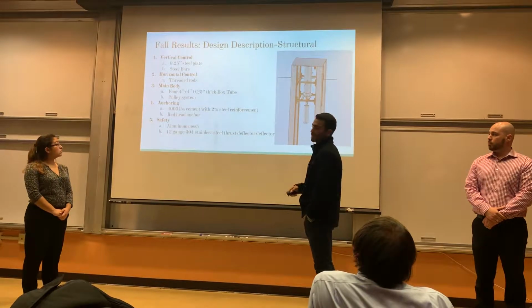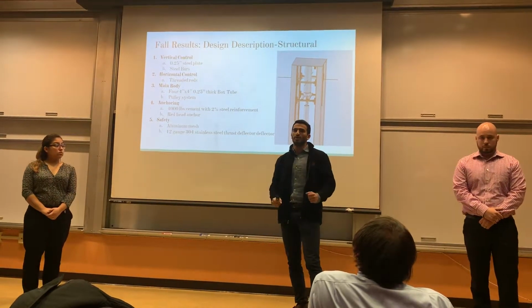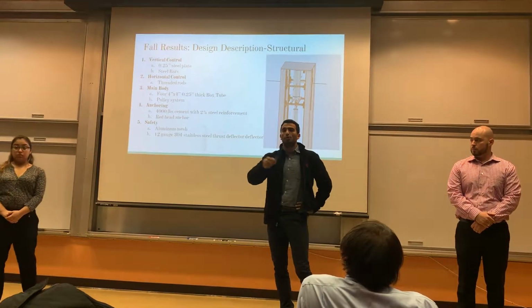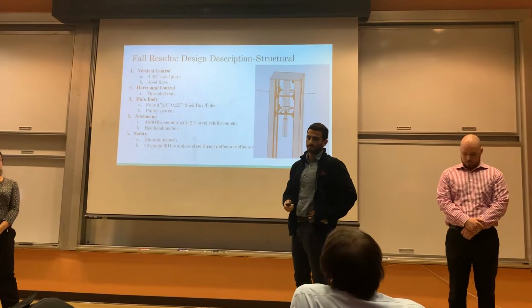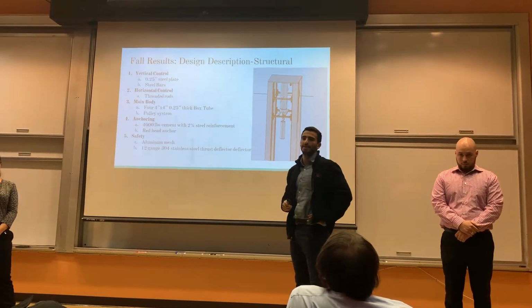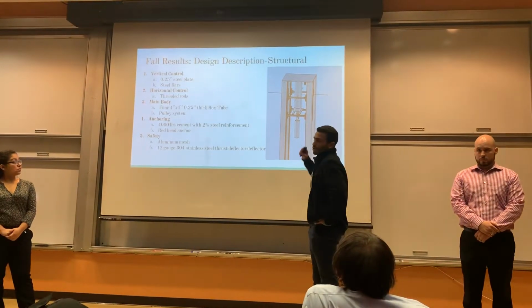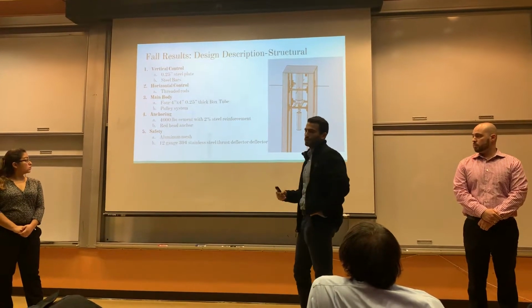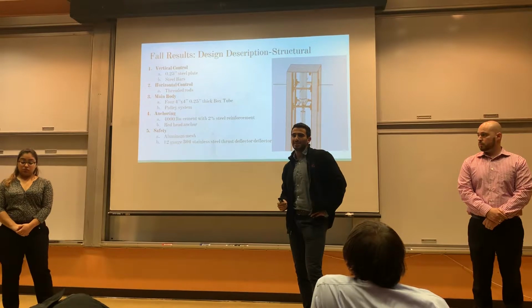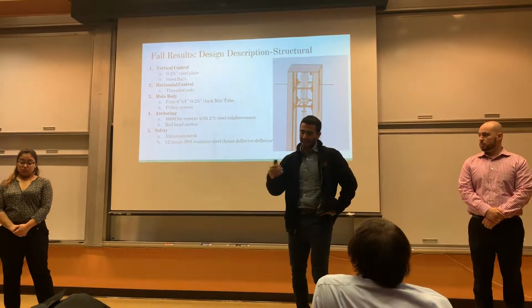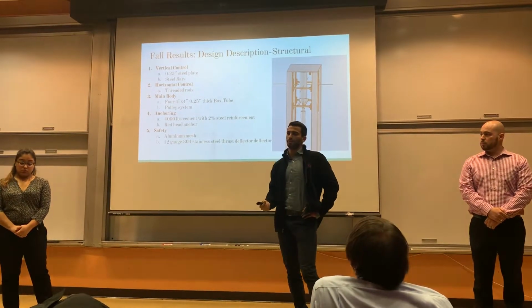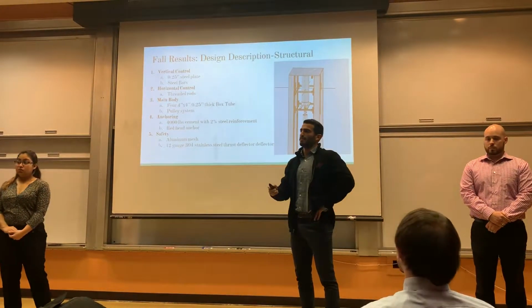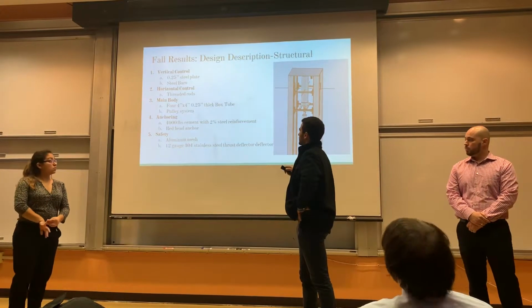And then anchoring, we went to the civil department. We were like, okay, we have an issue with that. They recommended a certain concrete that we can use, and with 2% steel as reinforcement. And then they also told us how we can manage to anchor the test stand to that concrete using a Red Head anchor. We're looking to do more analysis in that. That was just word of just relying on the professors telling us what we'd be able to do. I believe it was Dr. Mina from the civil department. Hopefully we'll have a stress analysis on that through SolidWorks.